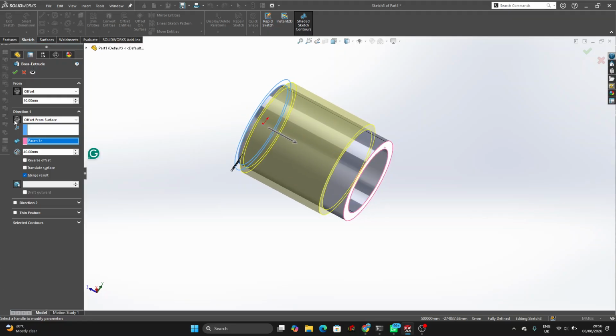So when you see back, there's a difference between reversing the direction of offset and reversing the direction of extrusion. What I'm doing is reversing the direction of extrusion, and it's not meant to be so. I don't need to reverse the direction of extrusion because I'm initially going in this way and the surface I'm dealing with is here.